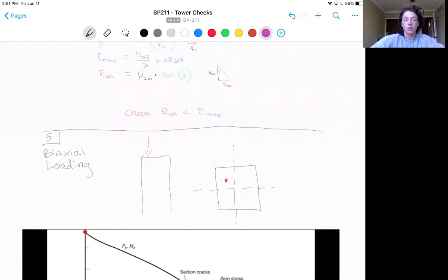Remember how the structural portion of the tower acts as a reinforced concrete beam, checked earlier, and a column? Now we will check it as a column under an eccentric axial loading, which I show here in the diagram. Overall, it is not normal to see horizontal and vertical forces acting simultaneously on a reinforced concrete column. So what we'll do to check them is use a biaxial bending diagram.